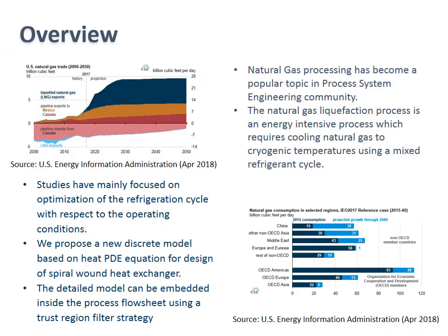Natural gas processing has suddenly become a popular topic in the process systems engineering community. The natural gas liquefaction process is an energy-intensive process which requires cooling natural gas to cryogenic temperatures using a mixed refrigerant. Studies till now have mainly focused on optimization of the refrigeration cycle with respect to the operating conditions, neglecting the design effects of the multi-stream heat exchanger.